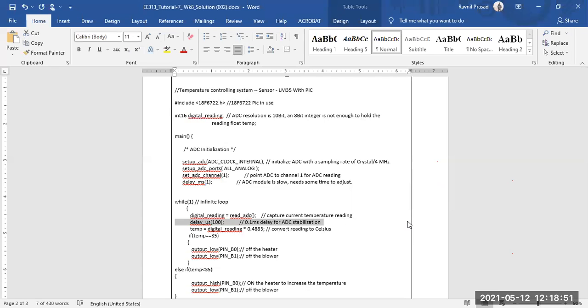We need to calibrate it or convert it into a particular temperature reading that we can interpret, right? Let's say from a sensor you get some wave count of 300, but what does that 300 mean? So we need to convert it into a sensible form. That is what we call calibration, right? So we need to calibrate that sensor, right?